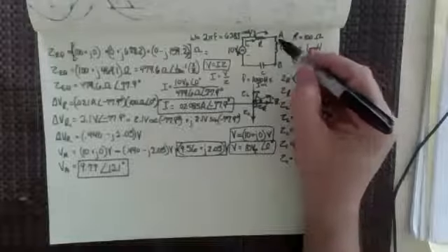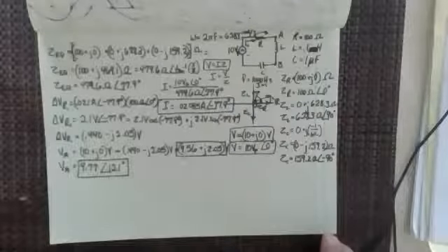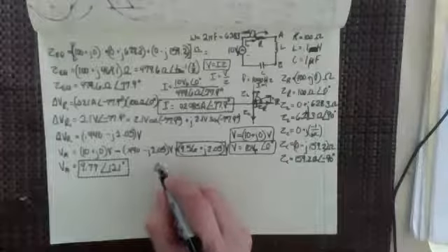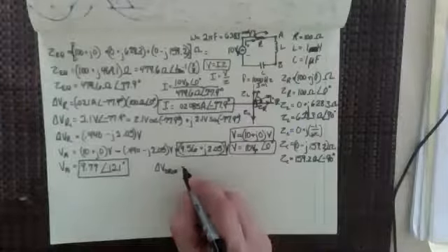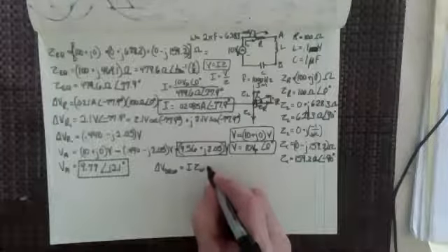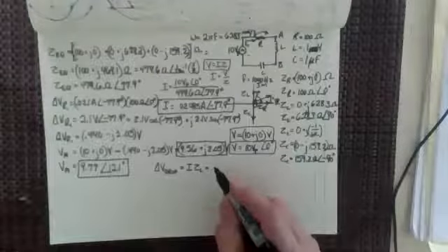We're going to jump over this inductor now because we're going to have a voltage drop across the inductor. And we want to see what that voltage drop across the inductor is. And of course, to do that, the voltage drop, I'm actually going to write drop here across that inductor, is the current through the inductor times the impedance of the inductor, isn't it? That's going to be the voltage drop. Remember, we have to subtract that off the voltage that we got from A. So let's see how we've got this here.